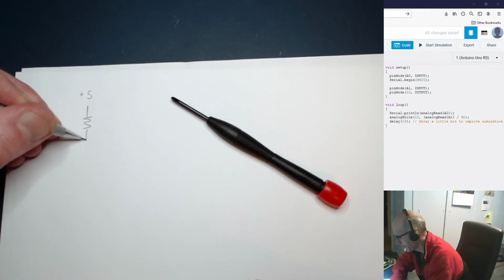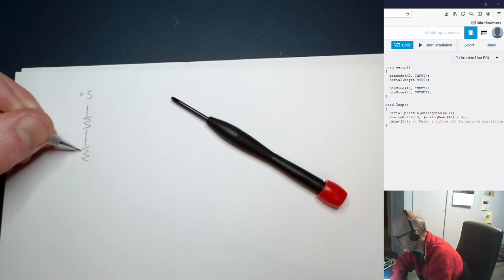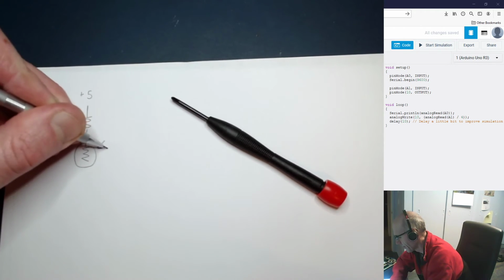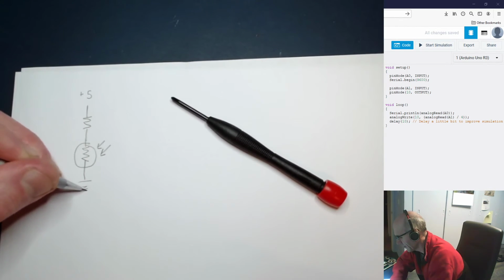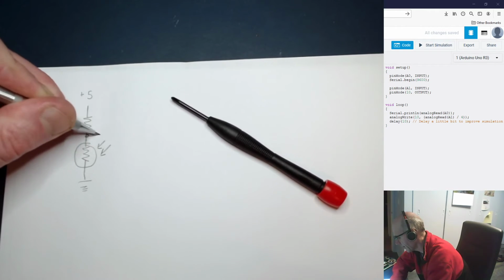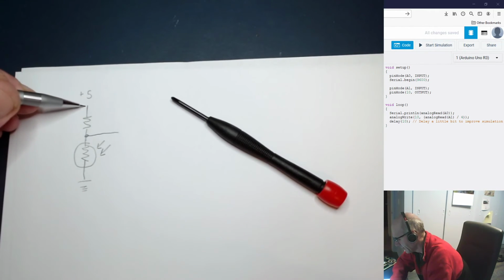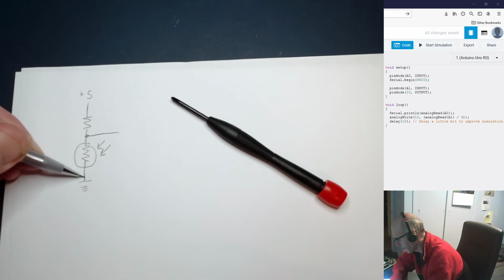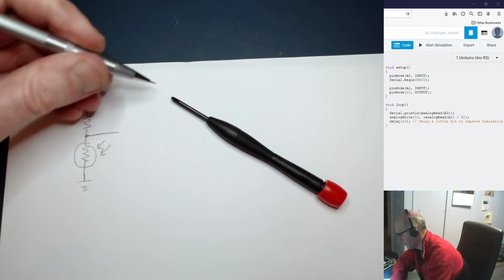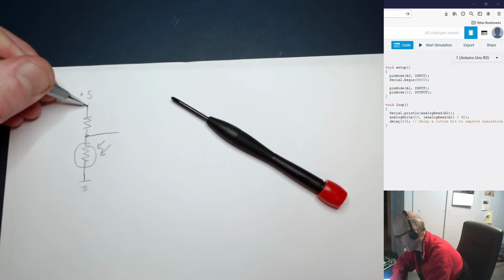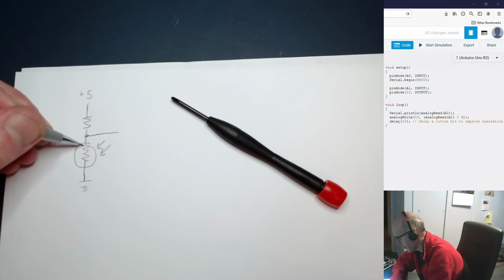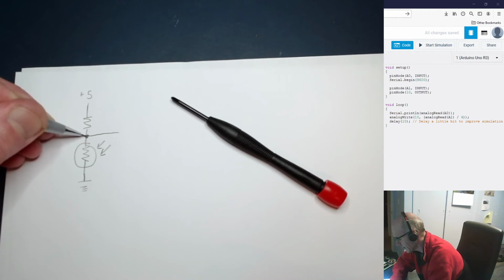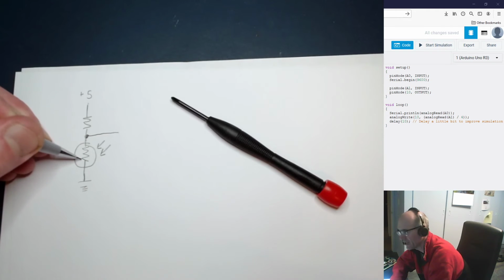You can probably relate. And then we've got a resistor right here, and the symbol for this is light falling on the resistor, and that's coming down to ground. And at this point, we've got voltage going back to our Arduino. Now, if I'm at 5 volts right here and ground over here, just as a potentiometer went from 5 volts on one side to ground on the other side, this does the same thing, except we're always fixed to this point right here.